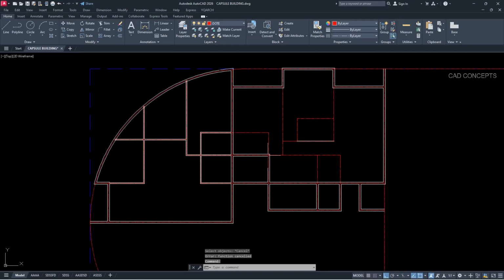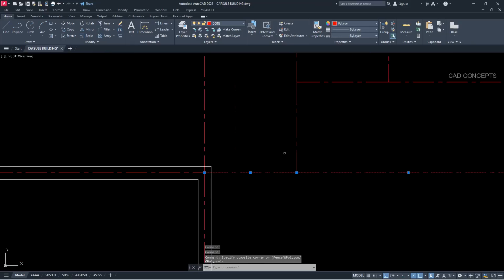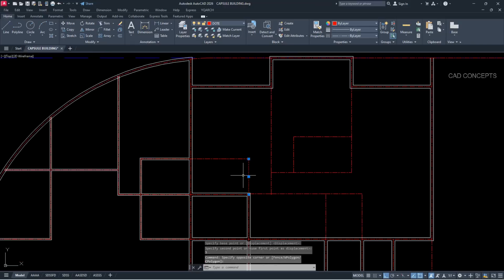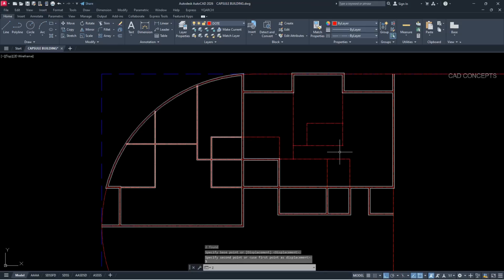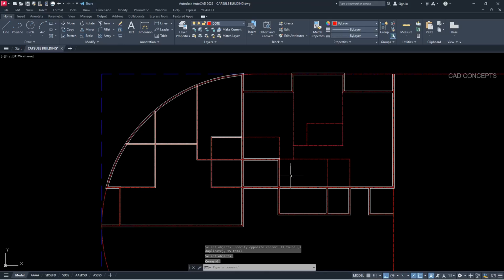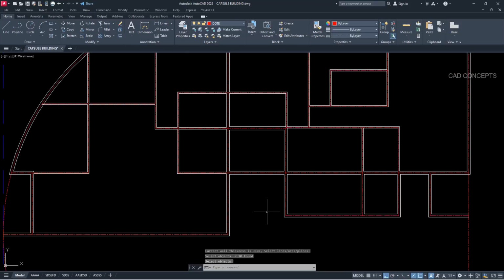And same here also. So let this 5 centimeter up, because 5 centimeter both sides will join to make 10 centimeter. Here also. And let this here inside, and this one also inside, because we will keep 10 centimeter wall. Now let this here 10 centimeter, select line, enter, repeat again, select previous, enter. So we are getting smooth wall inside 10 centimeter.